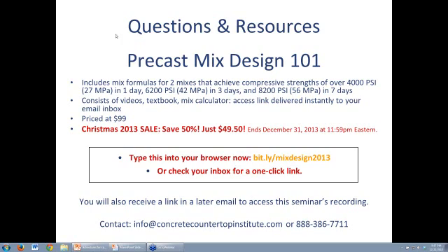I don't know enough about your mix design to help you any more than silica fume is going to give you very different work properties than VCAS or metakaolin. With my mix design, you may want to try less. If you're using like a 5 or 10% silica fume, that's about as much as you should go. If you're an Ultimate student, which I believe you are, just give me a call because you have my phone number. We can talk privately.